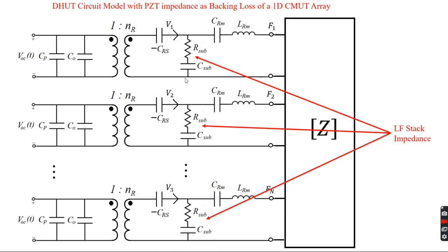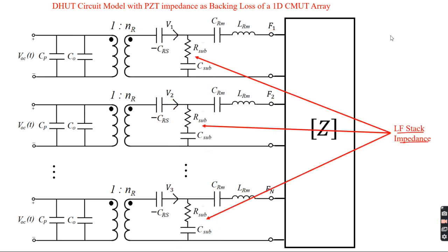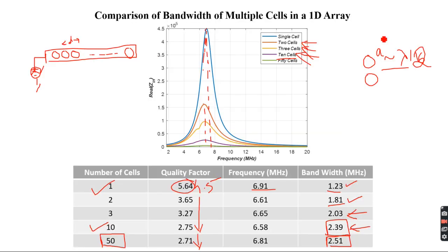Okay, so for example, if the high frequency is CMUT, because in medical applications you have harmonic imaging, a transmitter can be transmitting at a low frequency, and at high frequency you're going to receive it. So the low frequency is the transmitter part, high frequency is the receiver part. So in such a hybrid architecture, you can have a wideband response, much wider than this. Okay, you can have much wider than this. So that's just the story.